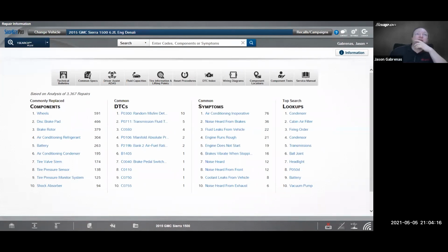One of the most common causes of shorts to ground or power? I don't really know. It kind of depends on the vehicle, I would say. But I would say the most common failures you're probably going to see, at least in my experience, are going to be failures internally shorted inside the module. Could be a flooded car, right? If the car was flooded, that'd cause all sorts of shorts inside the module.